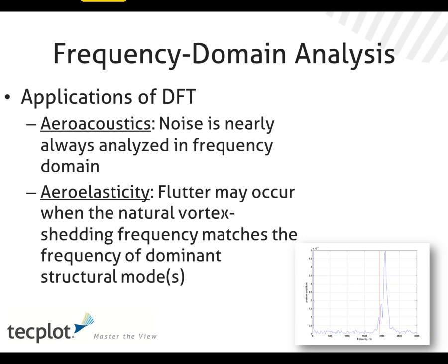But it's also valuable in other areas like aeroelasticity, where if you have a coupling of frequencies from the fluid dynamic frequency and the structural natural frequencies, you can actually end up with flutter and destructive flutter forces.